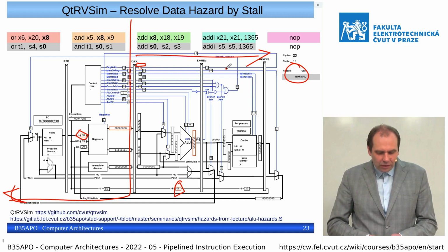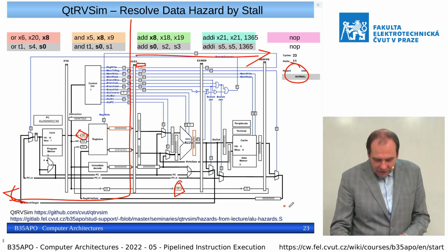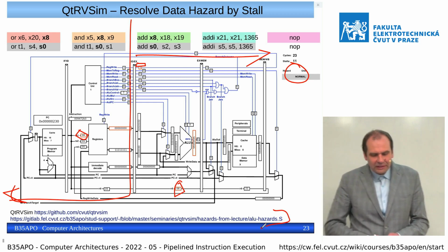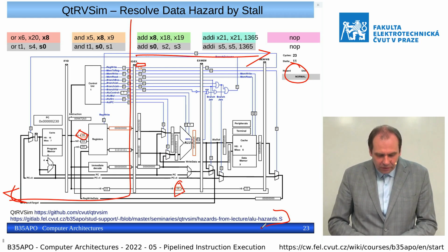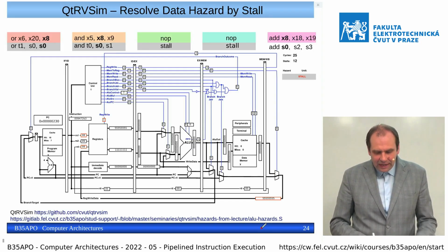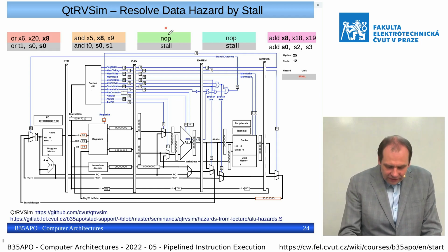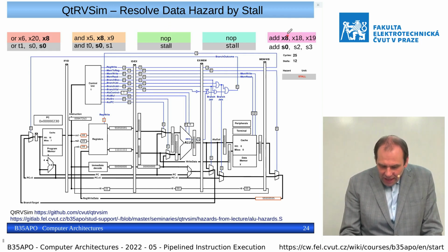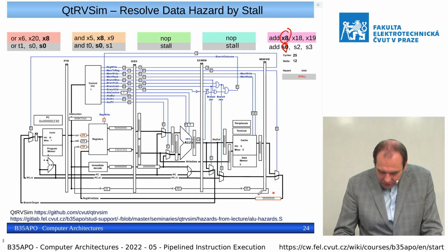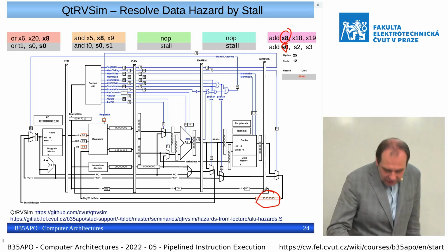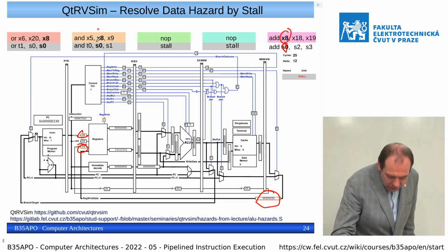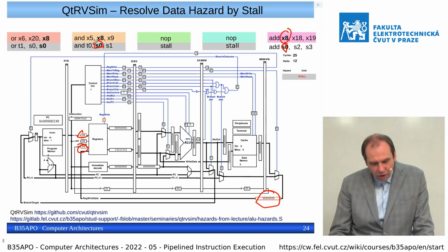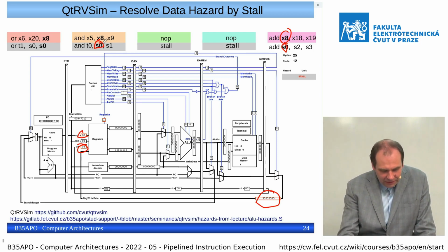So you can test it on our simulator. There is an actual path to the stat support repository where you have an actual example which I have there. So I step forward, and in this case, we need to wait 2 clock cycles till our instruction, which adds to the register x8 or S0, provides that value here as 555. There is the request to write to register 8. There is still information because this operation is stalled. It is basically kept at this stage.